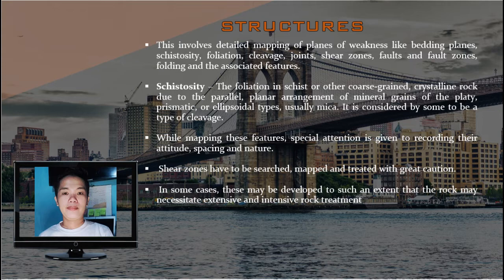While mapping these features, special attention is given to recording their attitude, spacing, and nature. Shear zones have to be searched, mapped, and treated with great caution. In some cases, this may be developed to such an extent that the rock may necessitate extensive and intensive rock treatment. Examples are excavation, backfilling, and grouting, and many more.